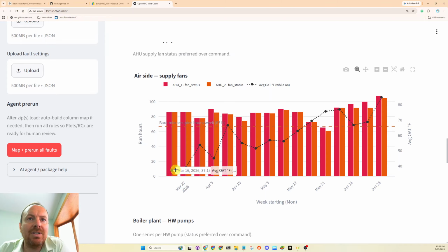This is degrees temperature outside in Fahrenheit. So in March, they're averaging about 40 degrees outside air temp on this axis over here. And then, getting into the 50s, springtime. So this is perfect economizing weather right here. In theory, we should be running bare minimum, especially when outside air temperature is in the 50s.